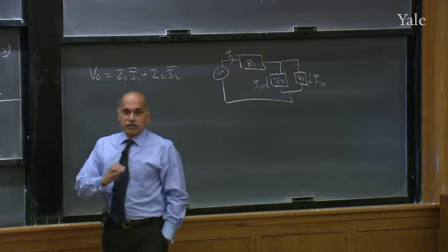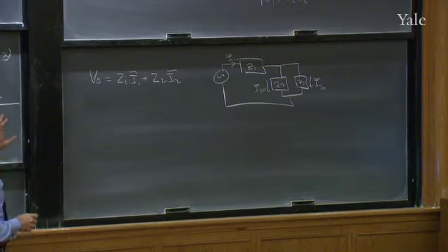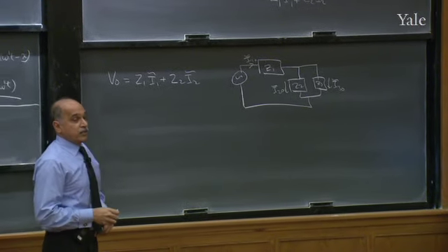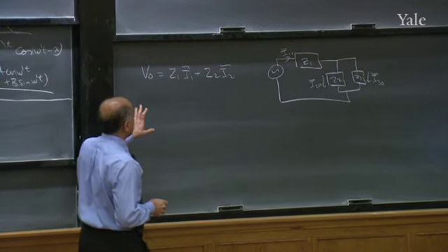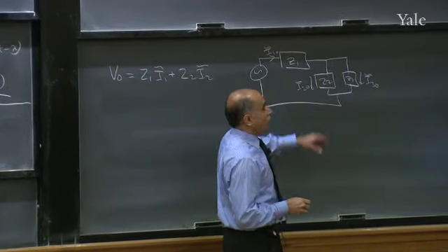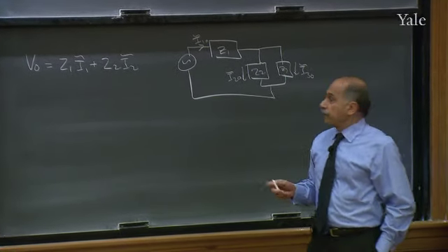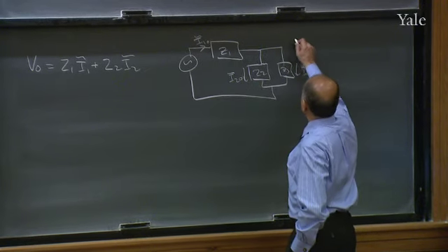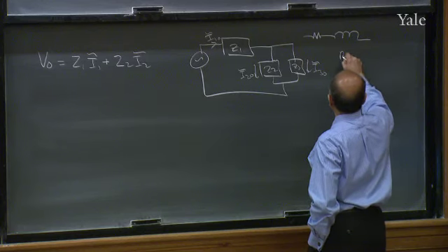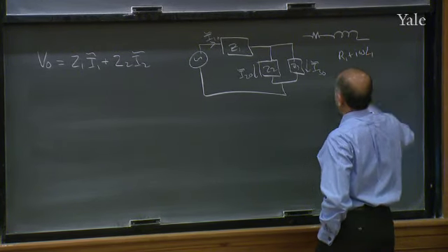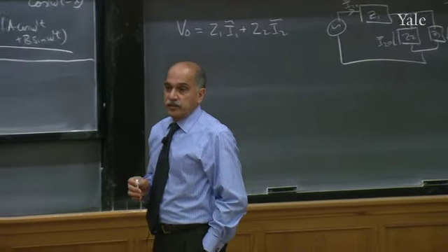And these constant numbers, they have no time dependence, obey the same equations as the real currents did in the real problem. So it's like a DC problem. The only subtlety is the impedances are complex. And the rule for impedance is very simple. If you open the box and you find a resistor plus an inductor, the impedance for that is R1 plus I omega L1. That's it. Apart from that variation, it is just like a DC circuit.